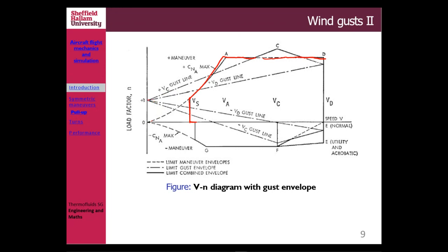following the equations that we've seen before, which is quite simple. But if you look at the CS25, there's another equation that considers the weight and the gust factor as well. Then you should be able to draw this positive gust line to point C and positive gust line to point D there. If you superimpose those lines on the VN diagram that you have, then in fact your VN diagram becomes like that. So that is the maximum that your aircraft could fly. Of course, the gust load here is within the earlier VN diagram, so what you take is actually the outside boundaries